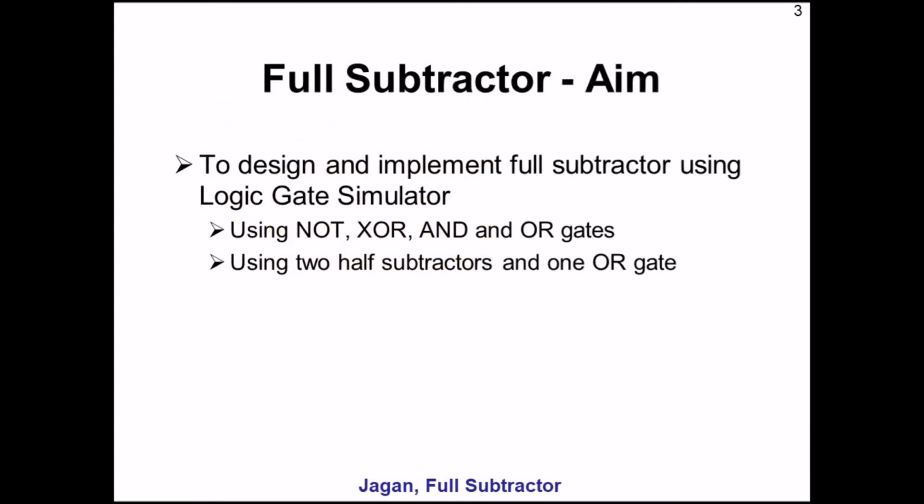So, aim is to design and implement full subtractor using logic gate simulator, and here you are going to have 2 tasks. One is with the help of the discrete gates, NOT, XOR and OR gates, you are going to implement the full subtractor. And second task, it's going to be your practice task, where you will be using 2 half subtractors and 1 OR gate to implement the full subtractor.